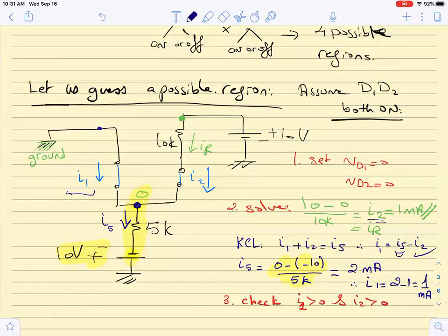But you agree that the way to solve for I1 is by solving KCL at the intermediate node, right? And this diode is not real. Later we will see how it fits into a certain circuit, which is a resistor and a voltage source. We replace it by a resistor and, in some cases, a DC shift when it is on, or by a simple DC shift.